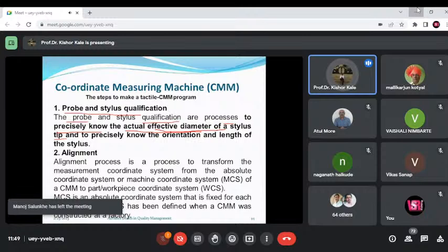Now how does this correspond for localization? I will explain how localization takes place. Correspondence for localization: in the case of a specified datum plane, a correspondence is established by fixing a datum plane in the measured data, and transformations are applied to complete localization. That means one surface, the datum plane, is fixed.